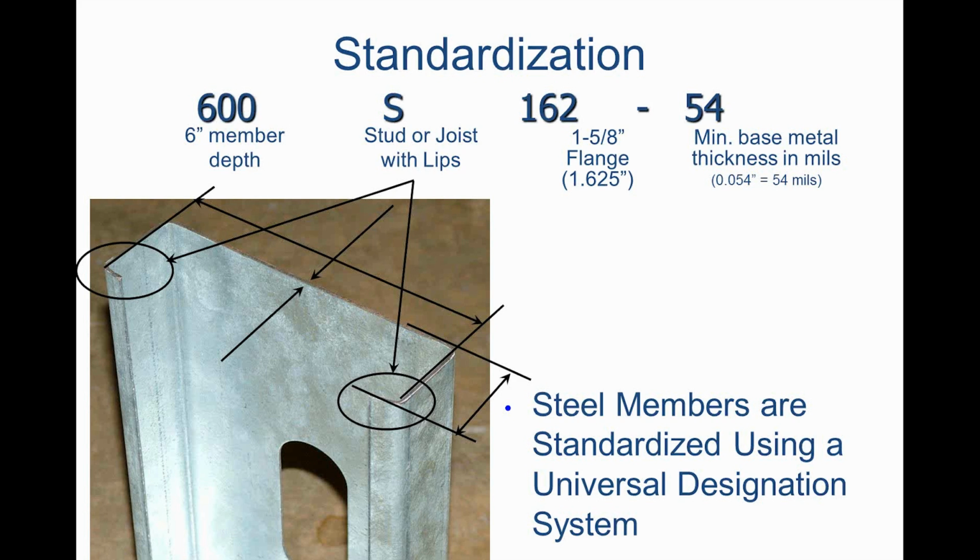So that's the only little nuance to watch with this: minimum delivered thickness, not your design thickness. Notice as we look at this designator, it begins to give us the geometry. It does not give us that corner radius. It does not give me the length of this lip. For that, S201 will have tables which will give those particular values. So using S201, we can define the entire geometry of our cross-section.